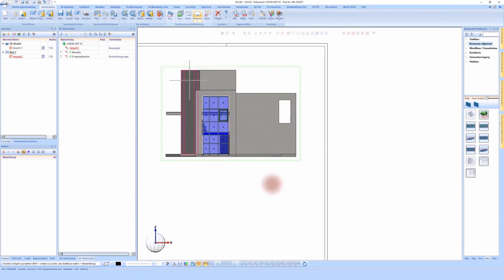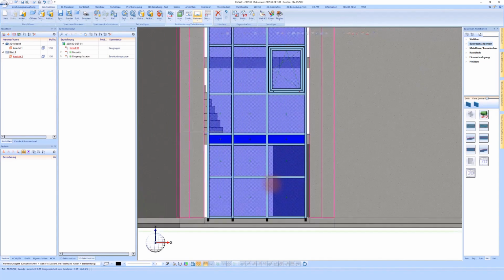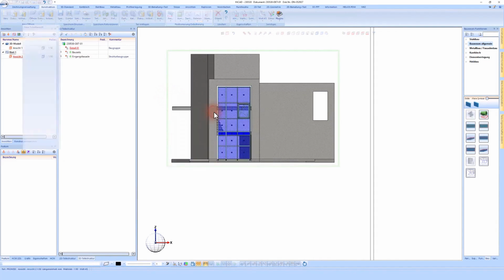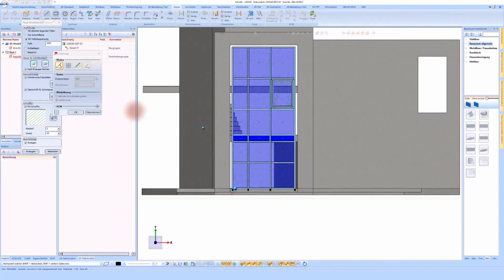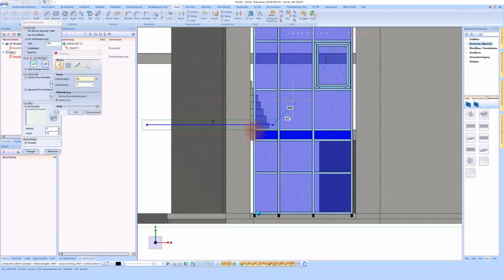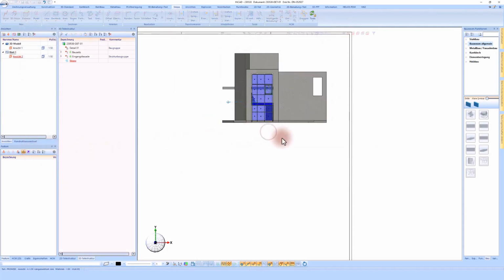This means that my first detail will be a horizontal section that is in this area. In this case, I will define a new section view where I say I want to create my section in this area. Here is where my section will be created. I can also set the depth limit in this case, which means it goes 1 meter down from this section. That is sufficient for me in this case. I can also specify whether the section should be limited, which I will now check, and simply create it.